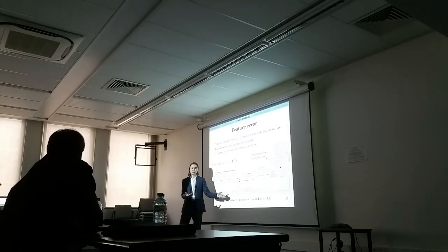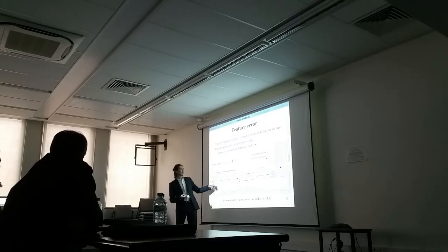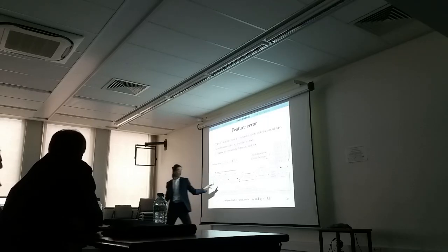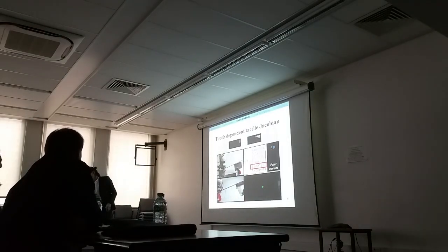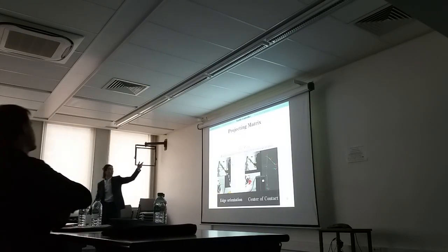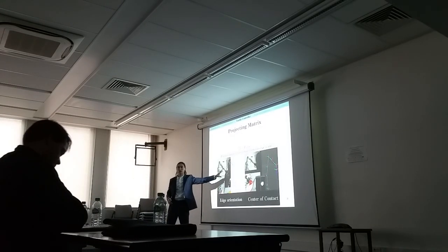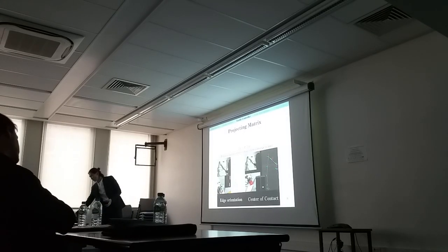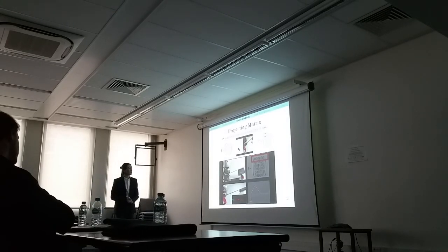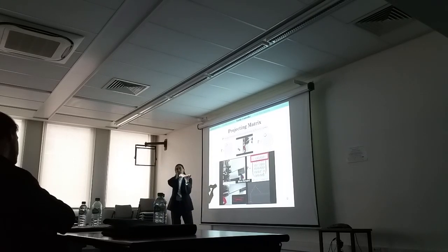But not always in the co-manipulation task. This feature is projected to the translational motion. That's why this is not only a selection matrix; we change with this. Afterwards, in the next slide, I show that those errors, even when they map directly to the rotations, can be projected to any other error in the Cartesian space. So besides switching between different features to control, we switch between different actions. For instance, when the first element of this projection matrix is 0, a robot can perform alignment with the bar.